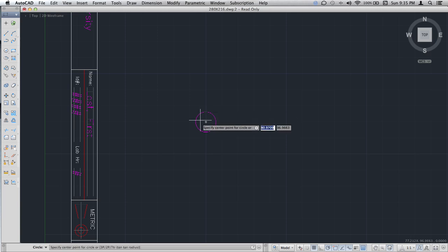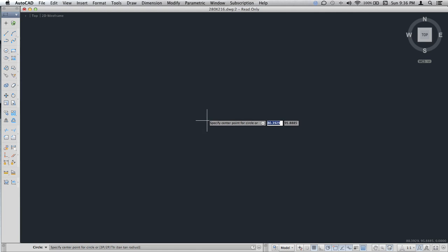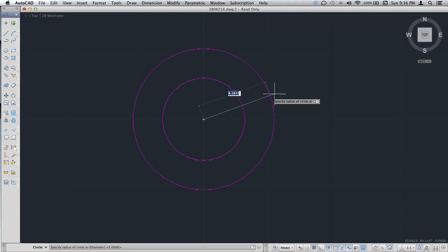Go ahead and hit circle, and that little green thing here is going to say I want to create a new circle that's centered at the center of this circle. Okay, so that's all I'm specifying, and you can check it by hovering over and seeing where you are. And this one needs to be radius of 10, so just hit 10. There we go.